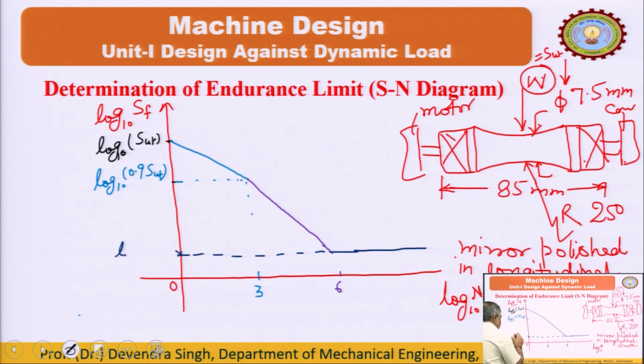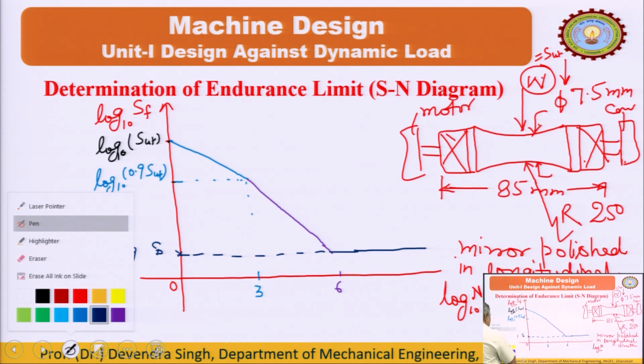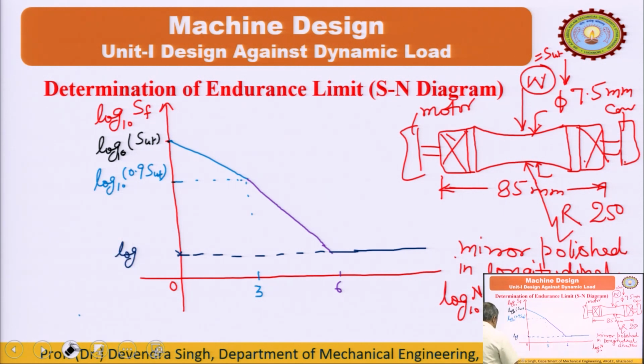This point we define as log S_E prime. S_E prime is the endurance limit of the specimen, and this is defined as the maximum completely reversible stress.